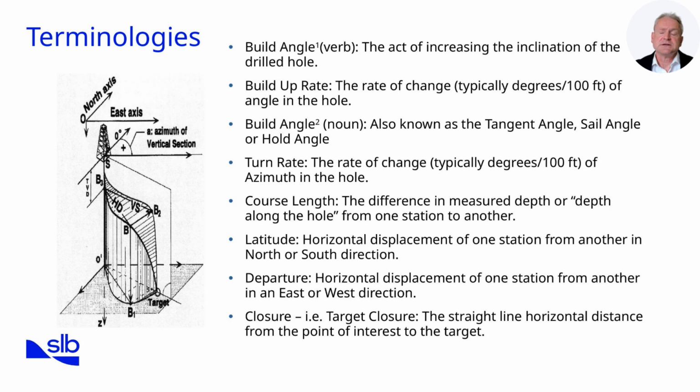Complementary to latitude is departure, which refers to the east-west horizontal displacement of the wellbore. Both latitude and departure values are calculated from directional survey data, and together they help construct the plan view of the well path. This is particularly important in pad drilling or multi-well platforms where spacing and collision avoidance are key considerations.